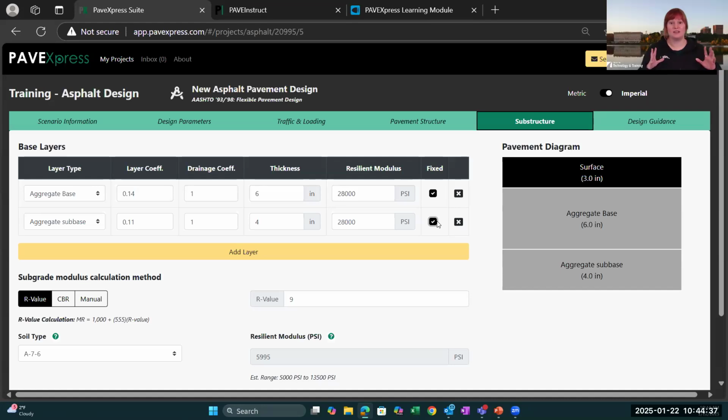And for anybody who's super new to this, constructability is based on what you could spread out and compact. Like what's the thinnest layer that you could spread out and compact to what you need it to be compacted to? So it's a nice even and sturdy layer. And yes, there are some limitations. You cannot spread out 2 inches of sand or gravel. If you have 2 inch gravel and you're trying to spread out a 2 inch layer of it, you're going to have some problems.